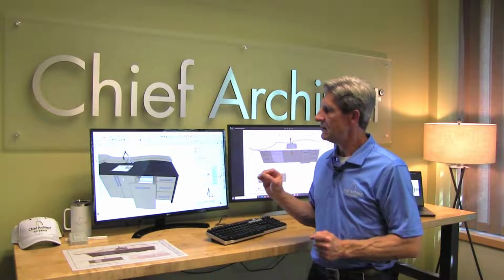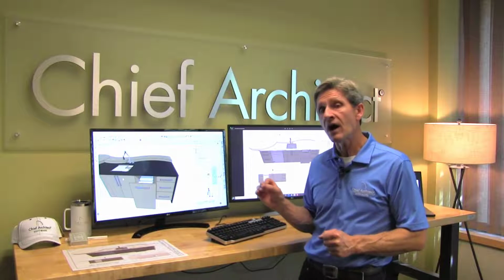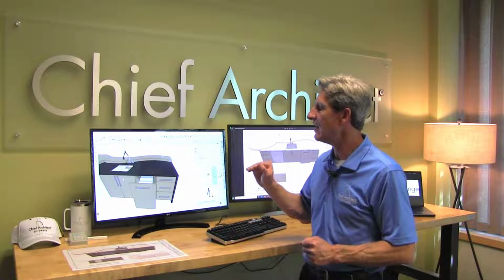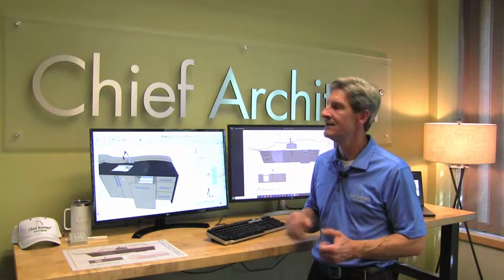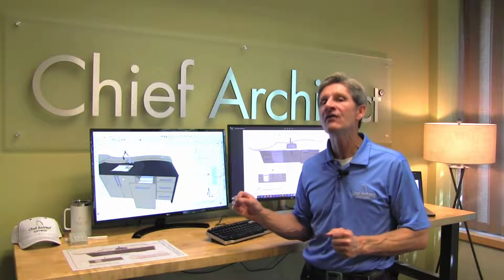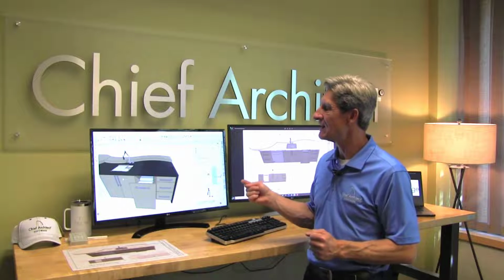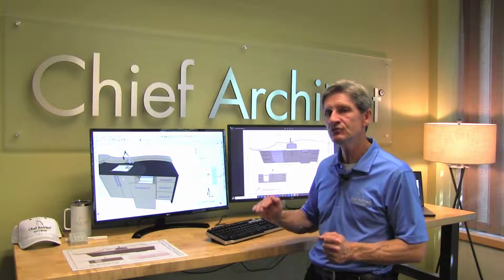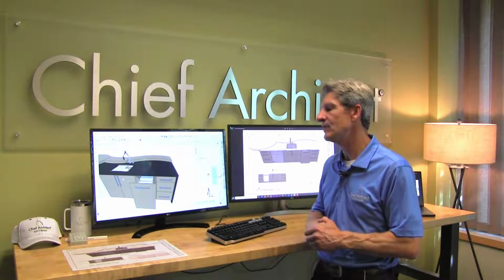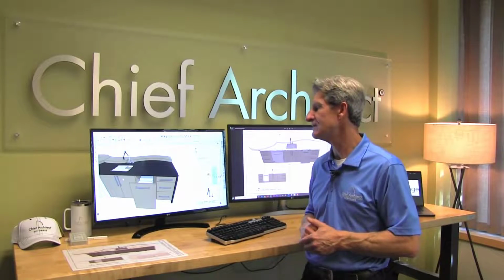But what didn't work as conveniently or automatically was the sink height and the faucet height. It was looking for the cabinet. My cabinets are 34.5 inches, and it didn't account for the thickness of the countertop, 1.5 inches. So I modified those items to move them up that depth. So slightly different issues with using cabinets without countertops and then just manually drawing those.